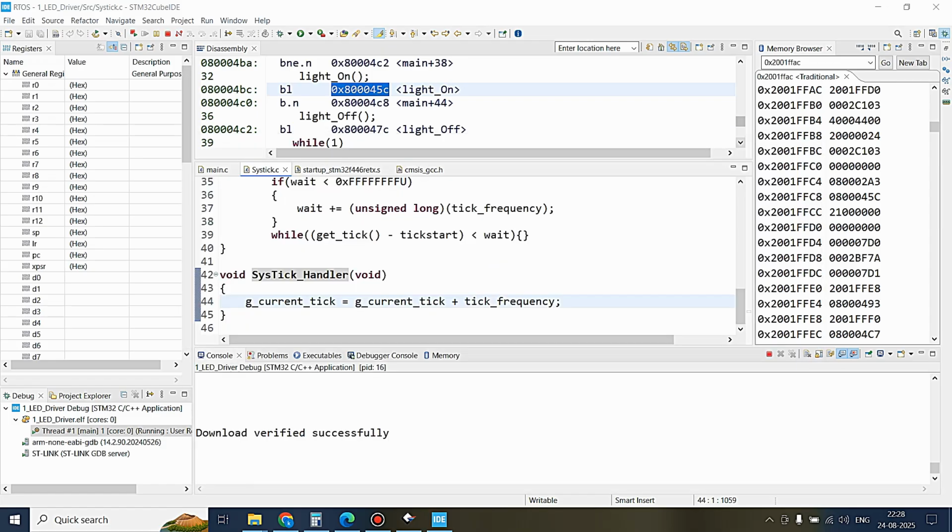This is how an RTOS actually operates with the internals of the ARM Cortex-M processor for switching from one thread to another, so that sequentially all the processes run in a periodic or certain algorithmic fashion. Based on the RTOS algorithm, this is done. I hope in this video you understood how the internals of processors are handled by the RTOS, and you learned how to manually switch from one thread to another, even though we have infinite loops in each of the threads in the program.